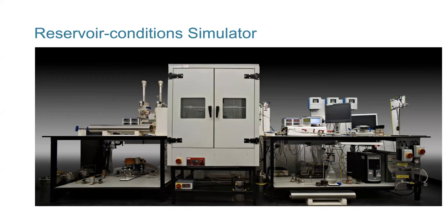And on this side, we call it the wellbore side, which allows the delivery, buildup of mud cakes, injection, bullheading, squeezing of fluids. The philosophy in all formation damage laboratories and approaches is to try to be as close as possible, simulate these operations, then produce or inject, and get to an end point so that we can compare to the reservoir and use that data to help us make decisions. That's the traditional approach, which I'm going to talk a little bit more about before talking about how we can take a better, more high-tech approach. So that's the typical wellbore condition simulator.